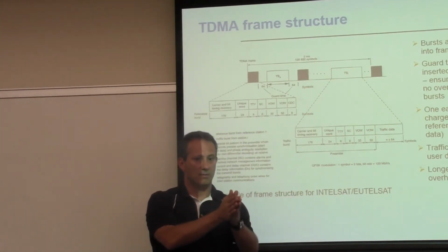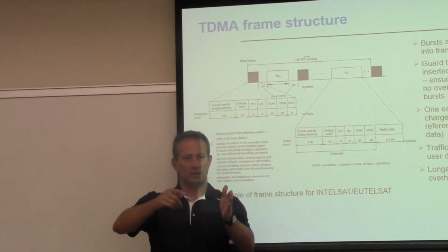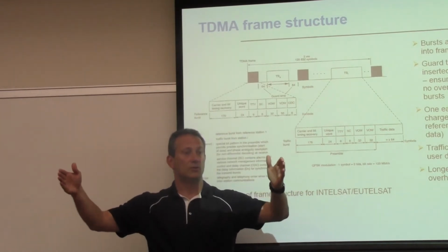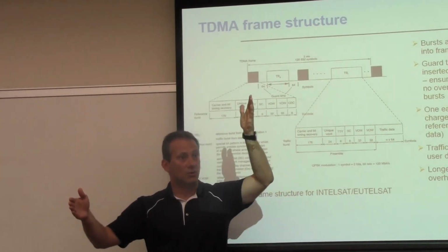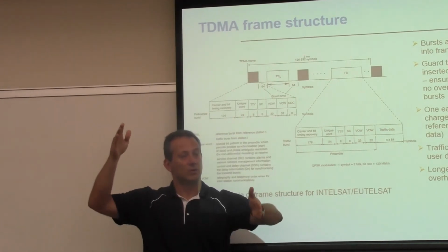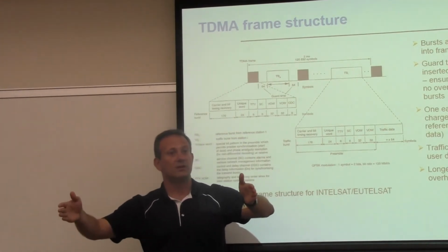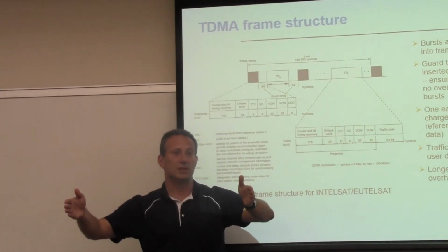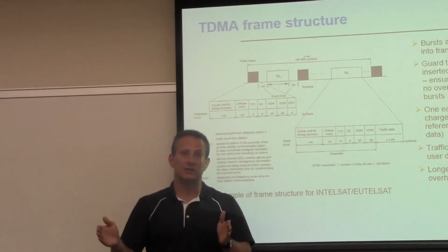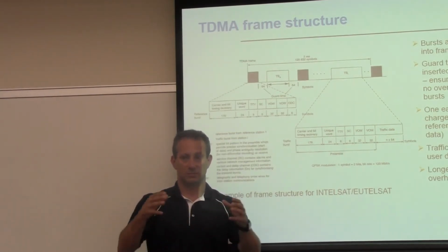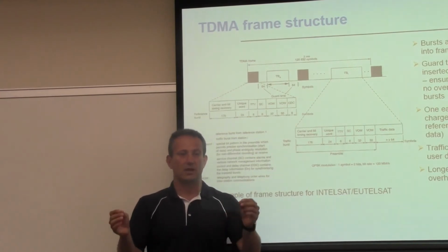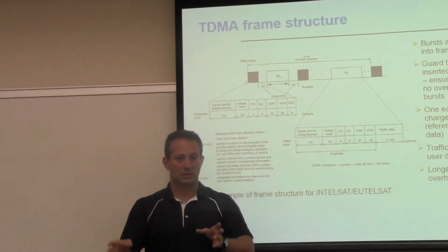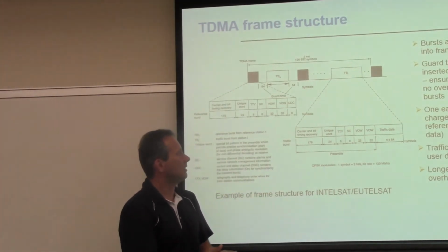But there are a multitude of phases, or many periods of your carrier frequency, within the duration of a symbol. For the operation of the matched filter, you have to know where the beginning of the symbol is, where you're going to start integrating, and where the end of the symbol is, where you're going to make a decision about what symbol has been sent. To detect the beginning and the end of the symbol, you have to find where those boundaries are. And the way we do that is we send these unique words that allow us, through autocorrelation, to determine the beginning and the end of the word.